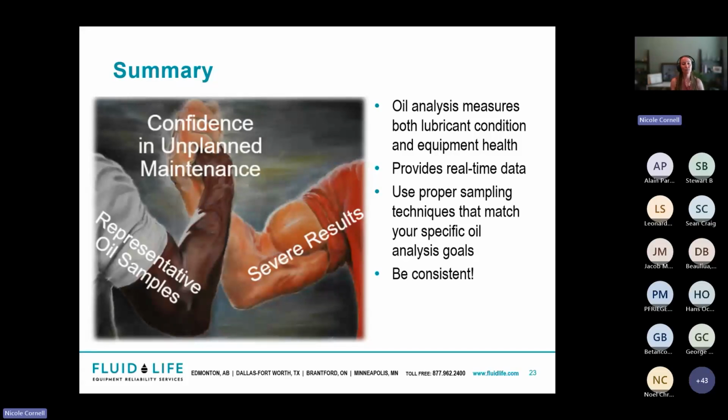You'll want to match the sampling location, frequency, and methods with your specific oil analysis goals and within your specific working environment. And last but not least, be consistent. Your oil analysis program is only as good as your sampling techniques, and you must be able to trust your results.